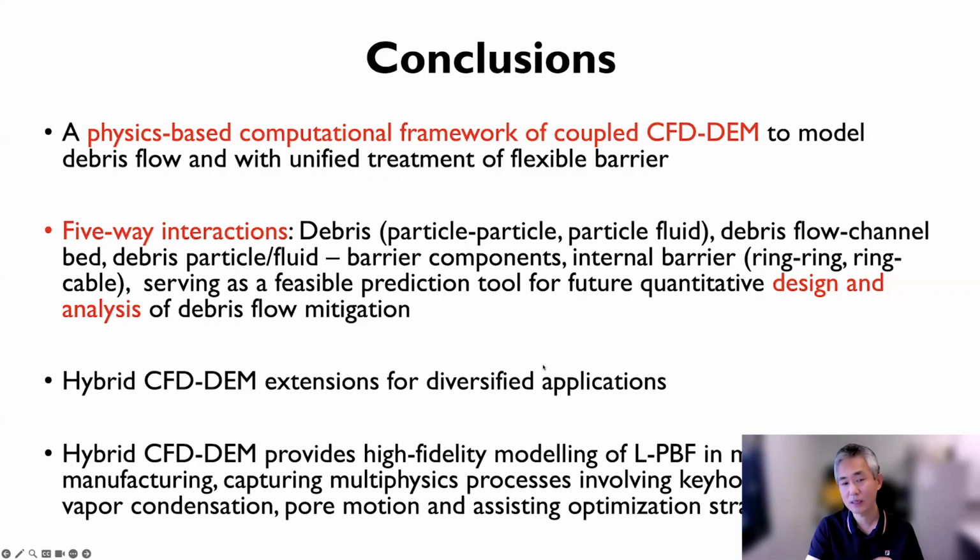And the second part illustrates how we apply this hybrid CFD-DEM to the modeling of laser powder bed fusion for metal 3D printing. We illustrate the multi-physics processes involved in the keyhole dynamics, the vapor condensation, the pore motion, and splitting, and then by the end we present an optimization strategy to try to reduce the occurrence of keyhole porosity.